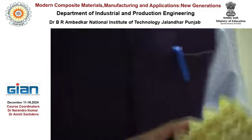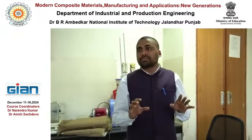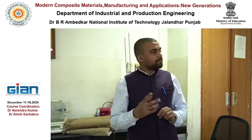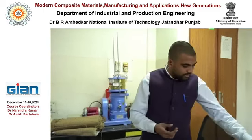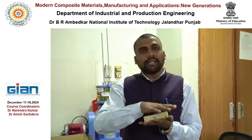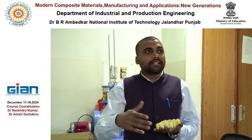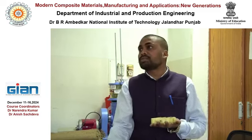And why does it become a stress concentration point? For this you must be knowing the composite failure mechanism, right? आप सभी को पता है composite failure mechanism. Whenever load is applied on the composite material, that load may be tensile, compressive load or bending load, the matrix material, the continuous phase, first takes the load, and it is distributed throughout the structure, and it is transferred to the reinforcement.